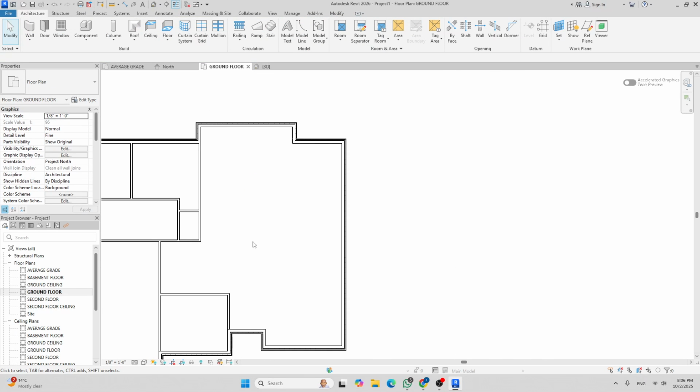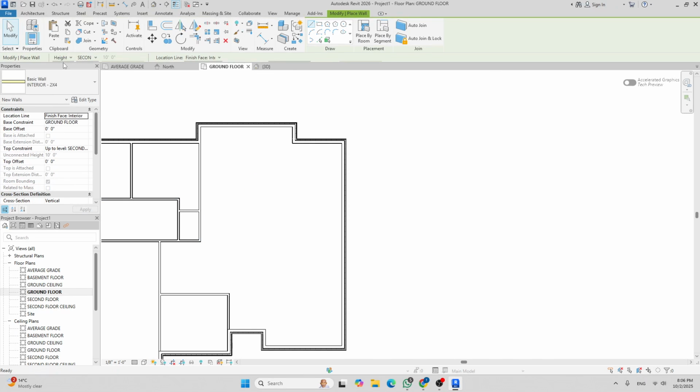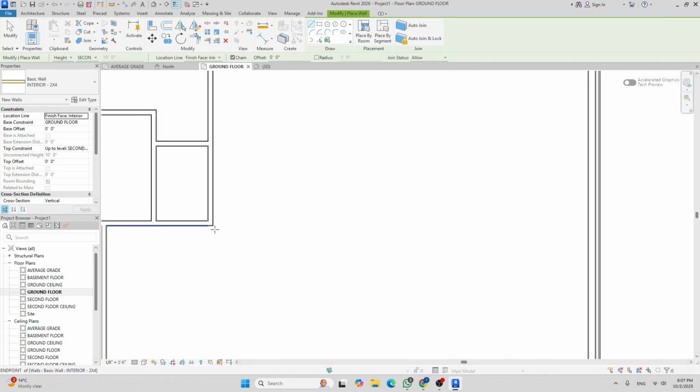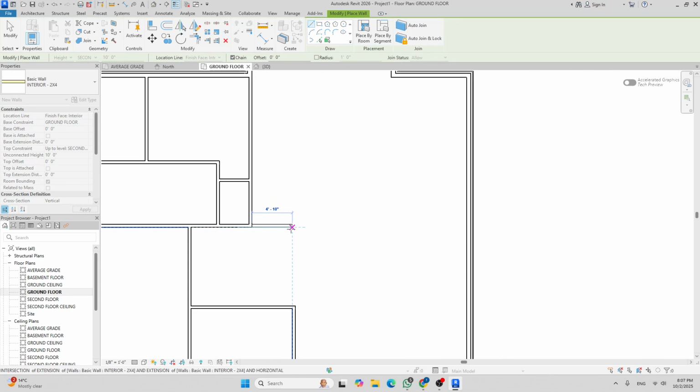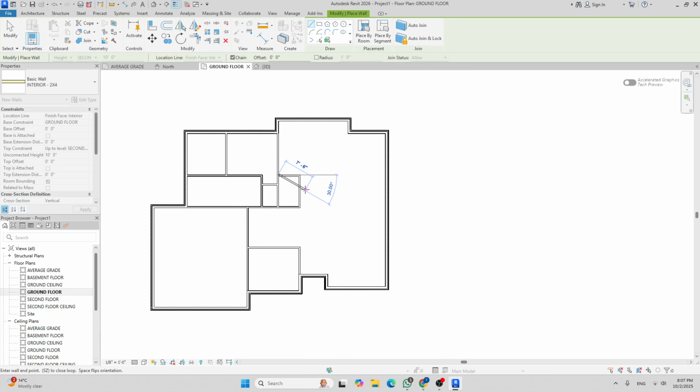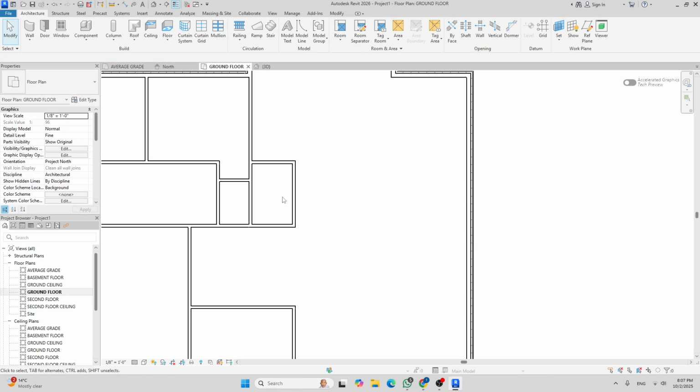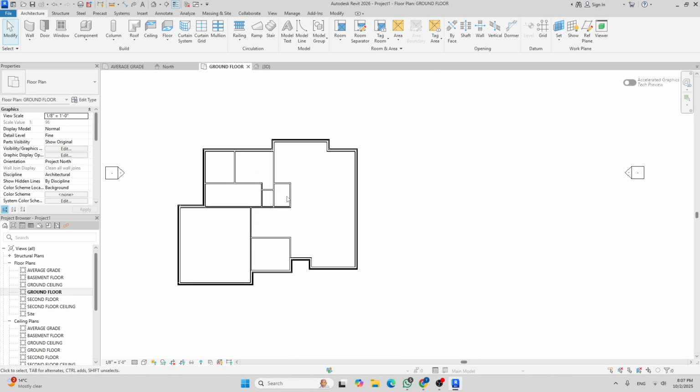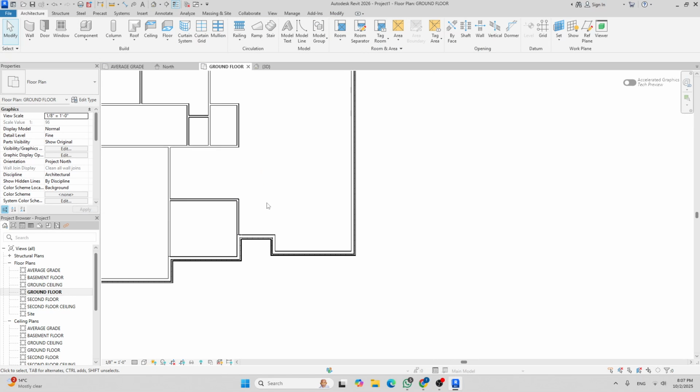And I'm gonna draw some other walls about here to the right until it snaps, and move up, hit spacebar so it flips, move to this side, hit spacebar so it flips. I'm gonna click, I'm gonna hit escape 2 times. Yeah, and now I'm gonna click drawing walls.